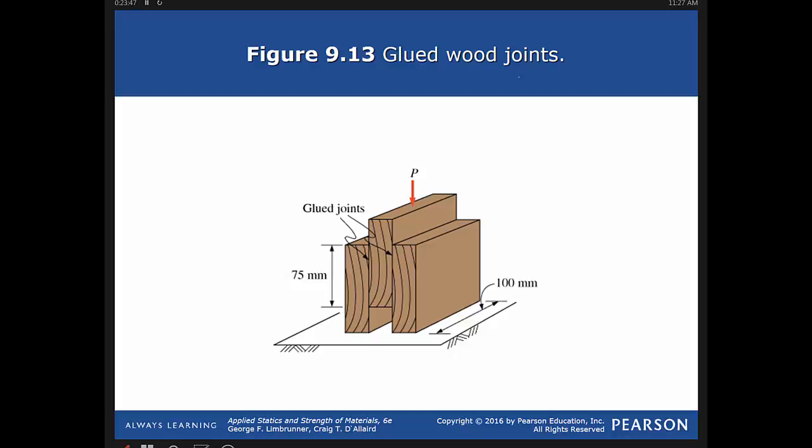So simply just putting in the numbers and plug and chug. But they did change that, the 50 kilonewtons, they're saying each one of those 2 surfaces between the middle piece, if you will, takes half of the load. You're having to assume that. In other words, the glued joint is exactly the same on both sides. Is that safe to assume? Not necessarily, and it's wood, so the wood might break before the glue would break, more than likely. But again, if you're ever dealing with an engineered beam, you could have some shear stresses involved, and that would be where they would look to something like that. You got your glued joint. That's exactly what's going on there, isn't it?